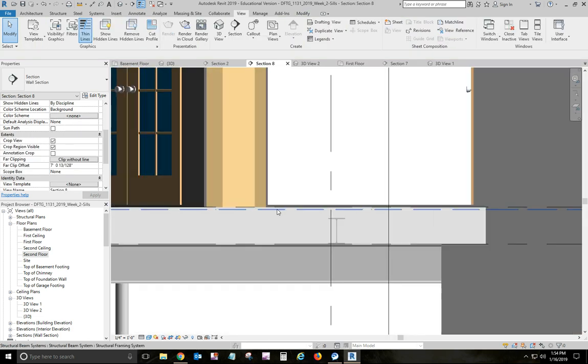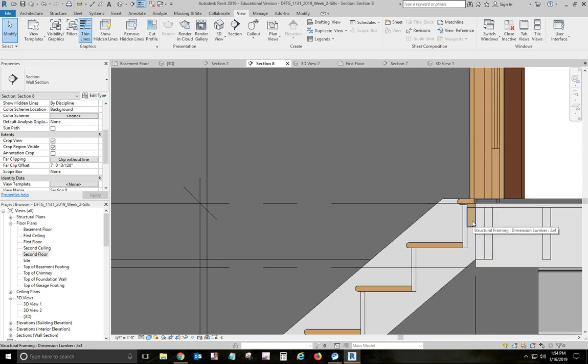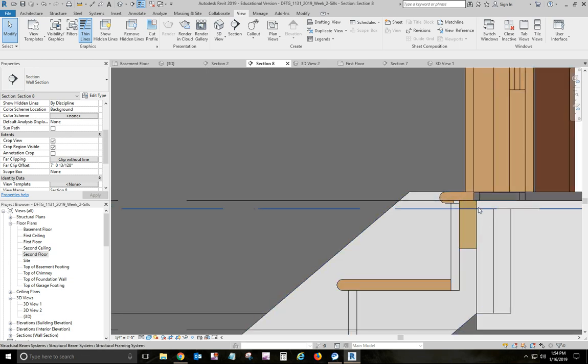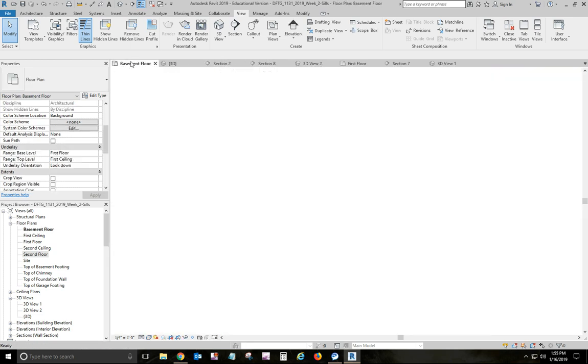Now, you will want to add, let me go to my section view here, let's see. Okay, the plans do show a 2x4 right here, blocking against the joist. So I went ahead and added the 2x4, and I brought my plywood subflooring out over the top of it. It's not showing up right there, but because we got all this stuff. But I've got the 2x4 piece here, and then I extended the plywood subfloor out to that point. All right, so basement floor.